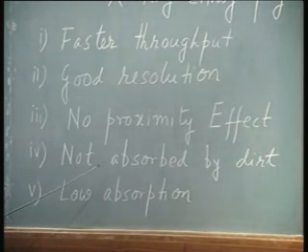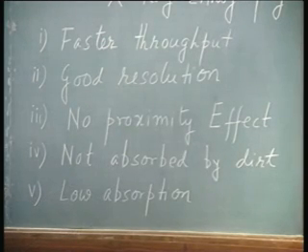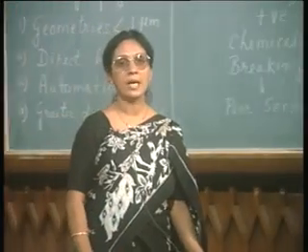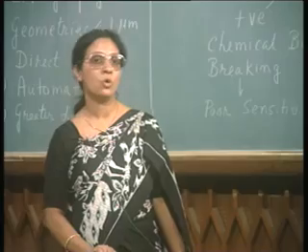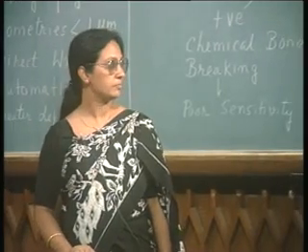Moreover, X-ray is not absorbed by dirt, so the presence of dirt on the mask plate does not materially affect the pattern generation. At the same time, X-ray has low absorption in the resist, and that also helps in the sense that the exposure is uniform and therefore, we can get straight walled features.